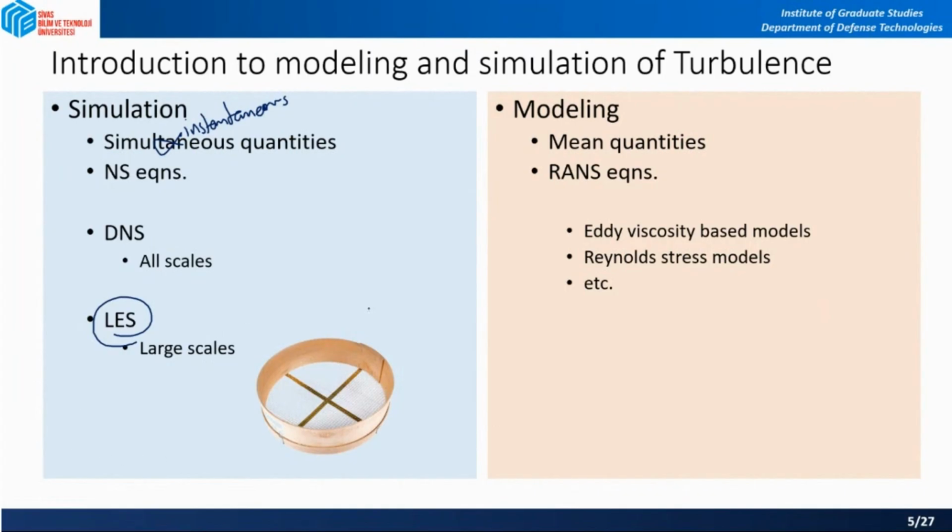What you see here is a filter. So you are using a filter to filter out some eddies. Exactly, LES, or large eddy simulation, does this. It uses a filter to filter out the large eddies, and then smaller eddies will be modeled.